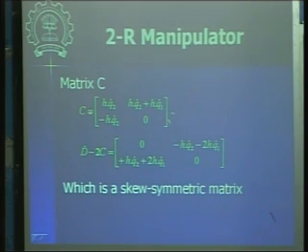Rather, for this matrix D dot minus 2C, you take this D dot minus 2C matrix, on this side you multiply by q dot transpose, on this side you multiply by q dot, and then you see what expression you get. You will find that it will be 0. So that is a property. If you form a quadratic by multiplying these matrices by vectors, you will end up with 0. So the quadratic expression for skew symmetric matrices is null, is 0.